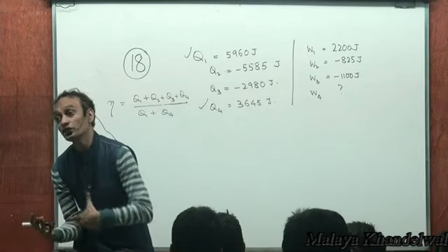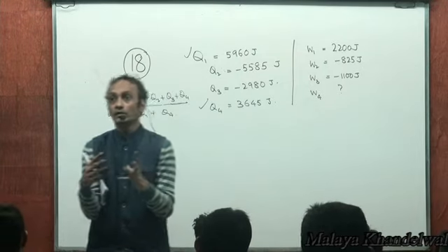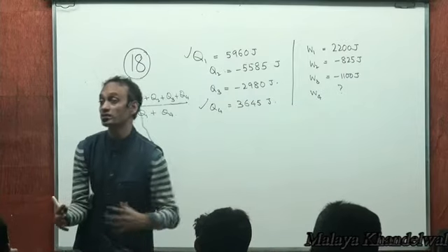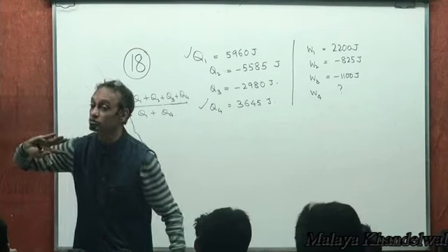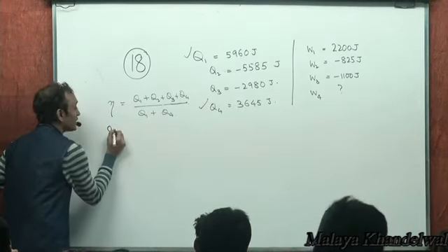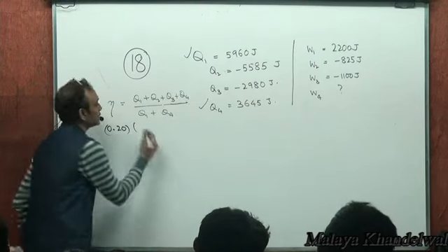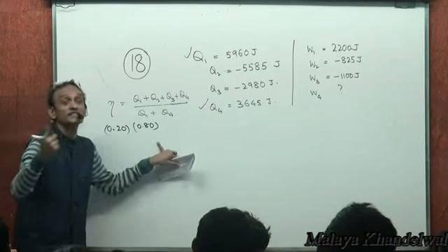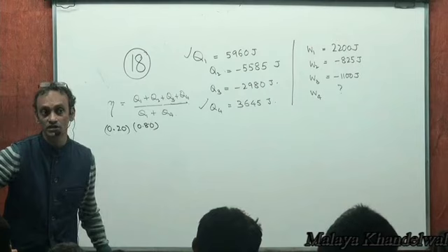Eventually only say 70 or 80% of what's produced by the cycle reaches the wheels. So if the cycle is 20% efficient and 80% of it reaches the wheels, that is only 16% efficiency, which again is good.